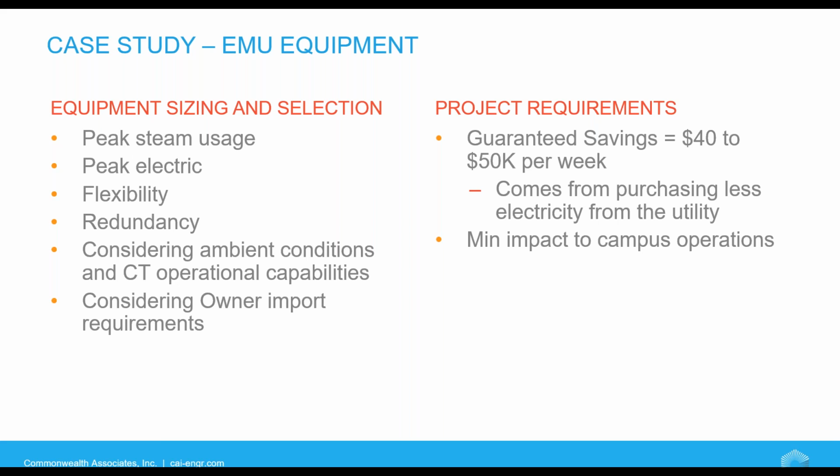And then one final criteria for this situation was the university's contractual obligations with their local utility. In this case, they have LDs if they export power when not called for, and wanted to ensure a consistent indraw from the grid, which was taken into account throughout the project. So for Eastern, there really was no benefit to oversizing the generator capability.